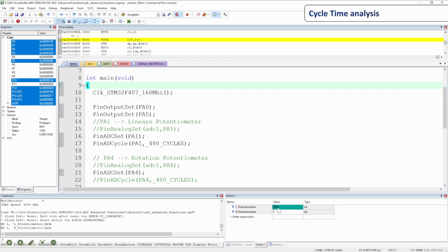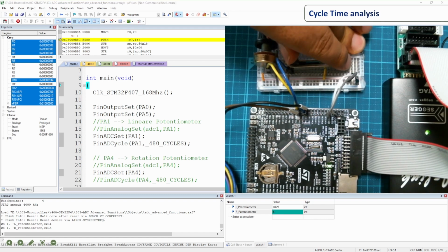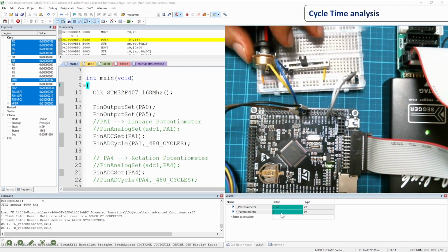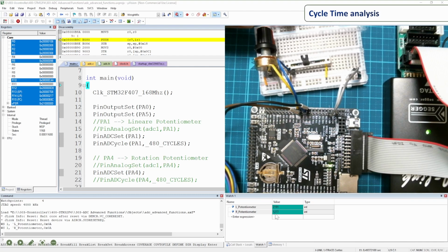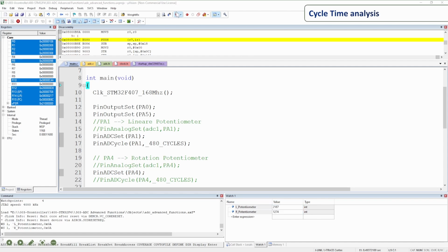small. So let me show you the video quickly. I'll be moving the slider now, and you can see that the changes are really small from the potentiometer perspective. When I change it, we do have a little bit bigger variation. But the noise at the slider potentiometer is smaller than the rotary one. Okay, so that was just a good view of what's going on here.